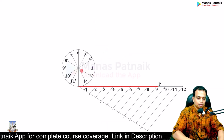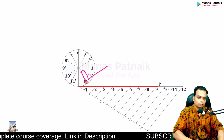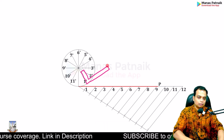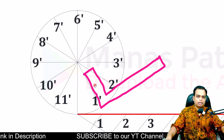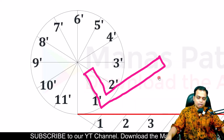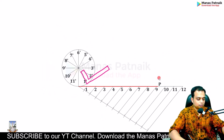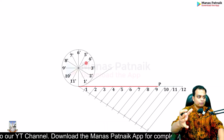How will you do that? Now keep your mini drafter over here like this, and then the short scale preferably along this spoke, 1 dash spoke, then the long scale will automatically give you the tangent. Something like this, and you need to repeat this process for each and every spoke. Let me do this in one go. Here it is.